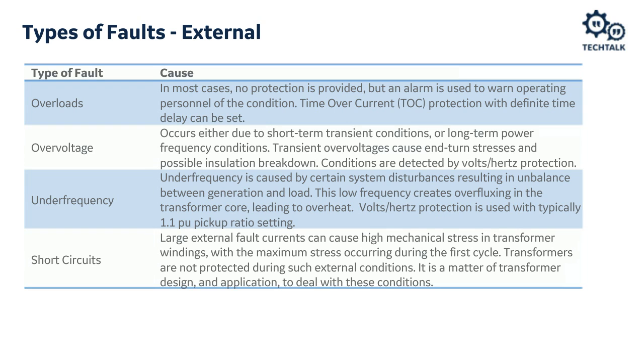The transformer relay can't necessarily tell where the fault is. It could be a bus fault, or it could just be a fault on one feeder. The specific feeder or bus relay should clear the short circuit, or worst case, the incomer relay below the transformer or the line protection relay above it will catch it, depending exactly which zone it falls in.